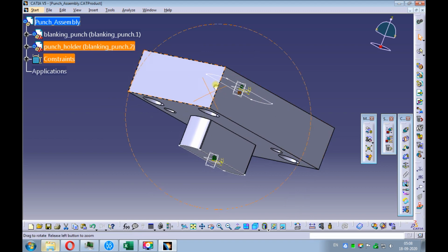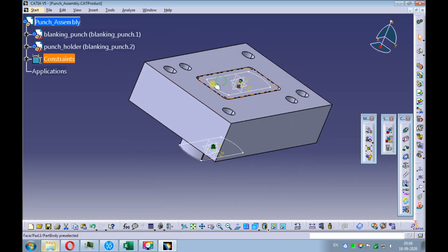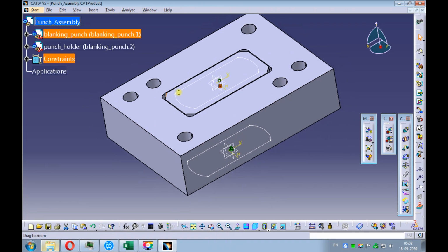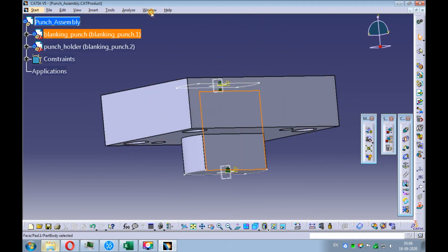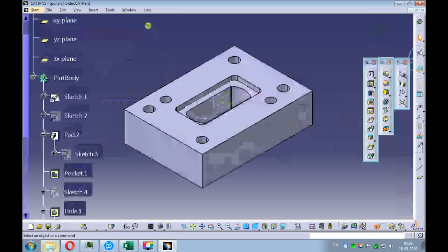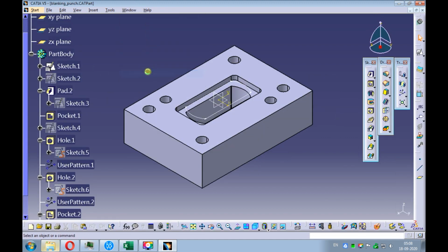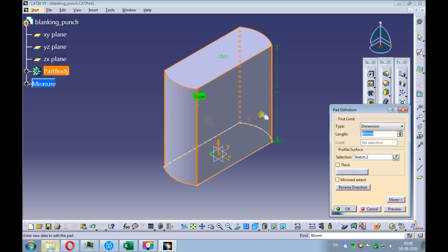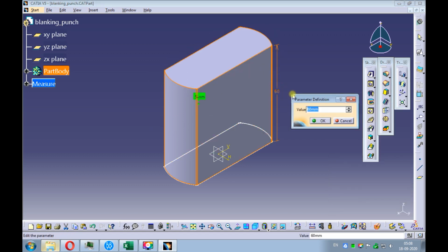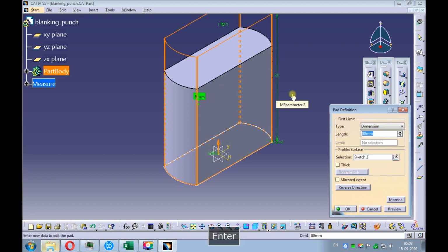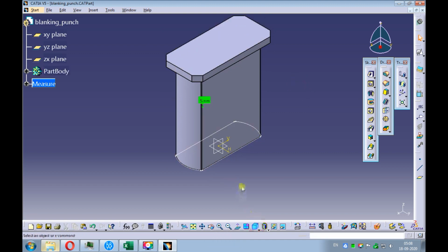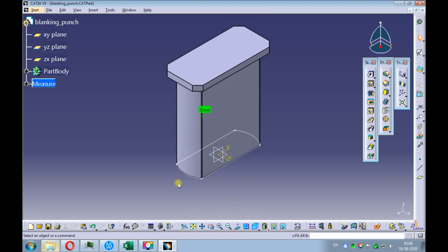Observe the punch looks short in length. For the time being, we will increase the length of the punch. We will finalize it later. Swap the window to the punch. Increase the length of the punch to 80 mm. Set the view to isometric and fit all in. Save the punch.